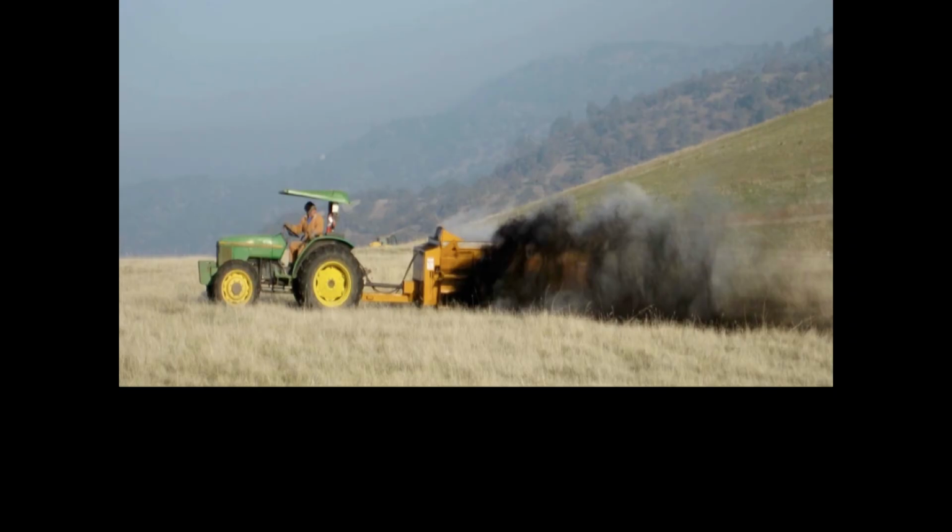sediment. The next question focuses on when the manure is applied. And the question is, was the compost and manure applied to pastures less than 2 weeks before storms that generated runoff? Research recommends applying manure or compost 2 weeks or more in advance of rain events that will result in runoff to provide time for pathogens to die off and nutrients to cycle, reducing the levels of both available for delivery to surface water.